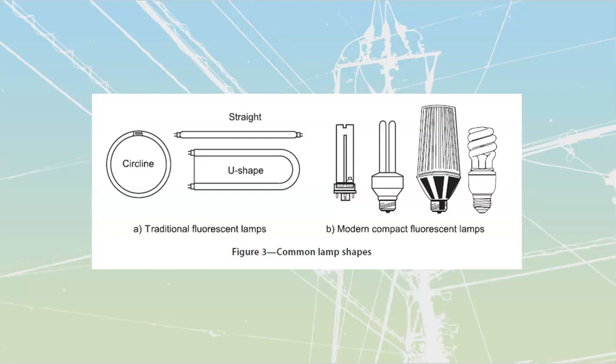Compact fluorescent lamps went through a bit of an evolution, and they start out over here, where they initially had these ones that had a bipin and an external ballast. If you ever saw these things in real life, they had kind of a flat pan shape. They have a little stabby base over here, with little pins off of it. You stab the bulb into that base, and then it gets connected over to its ballast. Through that connection, we bring power in. So the ballast was separate.